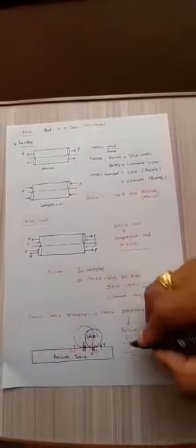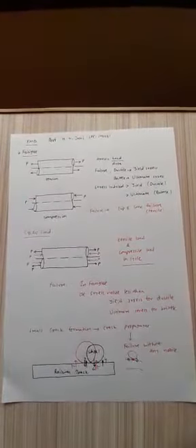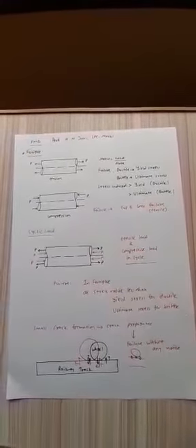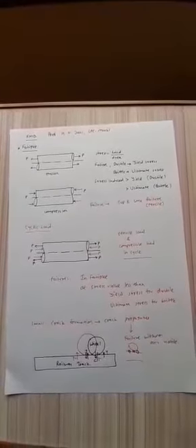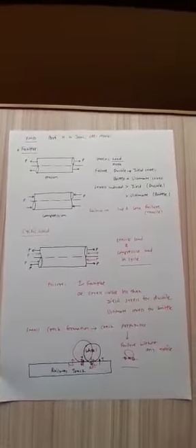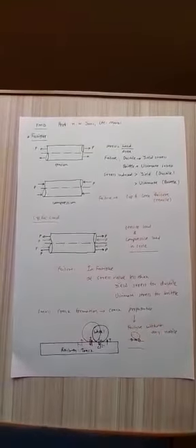The fibers which are nearby the wheel are subjected to tensile load. As the wheel moves on, the loads are continuously changing from compression to tension, and from tension to compression. So it is very dangerous. The fatigue application is very dangerous, and the failure occurs without any notice. So this is everything about fatigue failure.